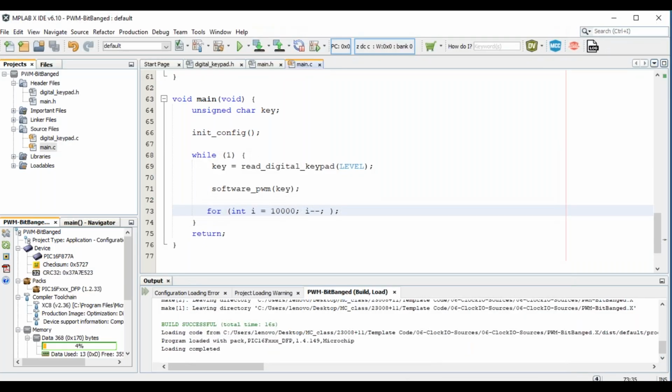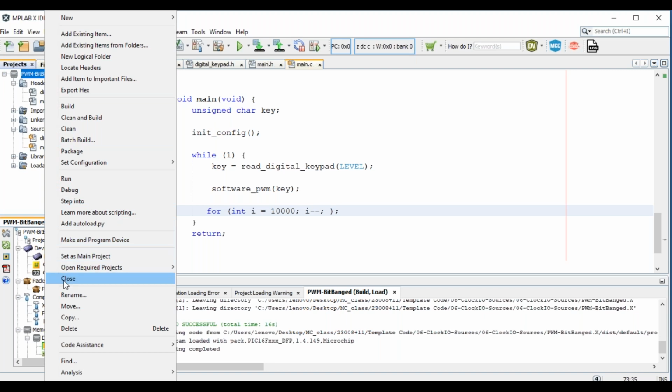Okay. So we are going to configure another peripheral. Our microcontroller comes with a built-in block which is capable of generating the pulse width modulated waveform of required duty cycle, also of required frequency. So you just have to specify how much frequency you need and how much duty cycle you want generated. That is going to give you a modulated waveform generated at a particular pin. Okay. So this time, let me make use of a built-in block to have a modulated waveform generated.